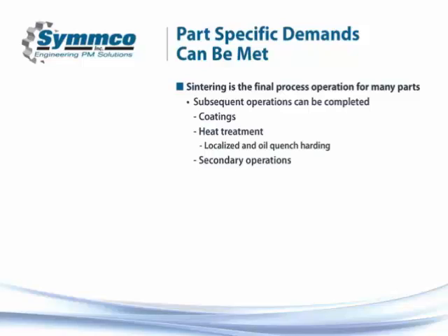Maybe even it's sinter hardening, which is the newer technology combined with very lean alloys specifically created to create that hardness right in our sinter furnaces, which removes one of the needs for a process operation. While heat treating is common, anytime we can remove that extra high heat and oil quench, it's very likely that we can help drive process variation down. So there are many keys to that technology that helps create a higher demanding product.